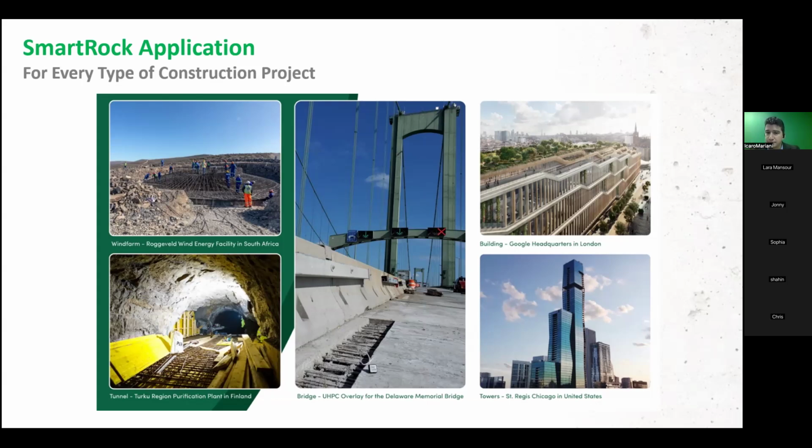So is this the mass effect you were talking about before, that has a downside when there's too much mass all in one place? Is that what you're saying? The pedestals are just a big lump of concrete, so they can have problems with the interior cooling at a different rate, or in the case of Texas, warming at a different rate from the exterior, especially during the day. I'm in Austin, which is not out in East or West Texas where a lot of this is. It's a 30 to 40 degree difference within one day. So this issue of differences in cooling rates has got to be a big deal.